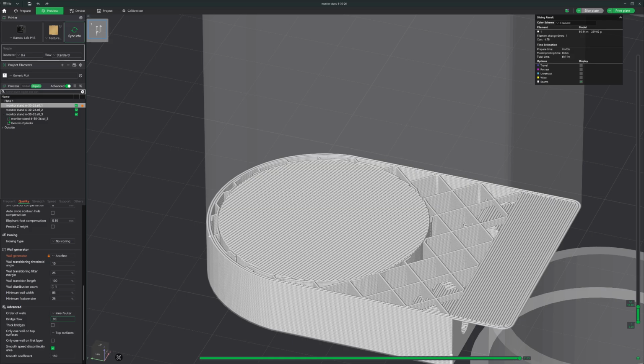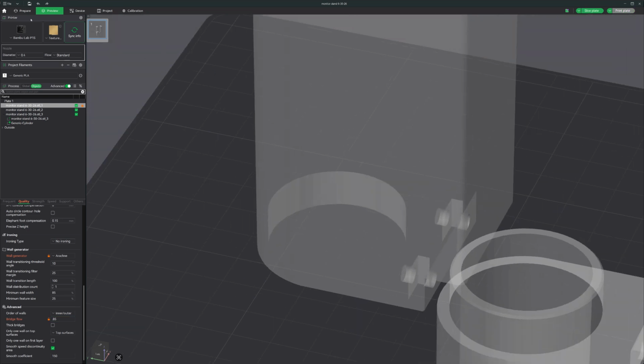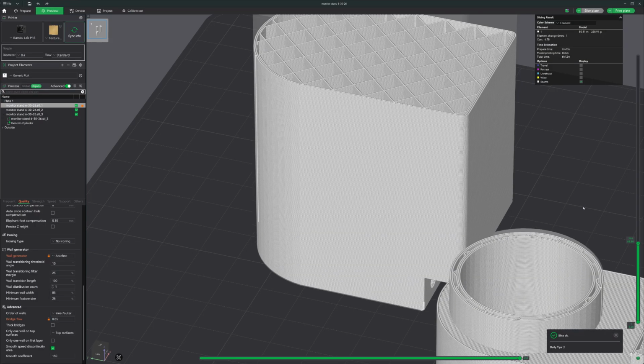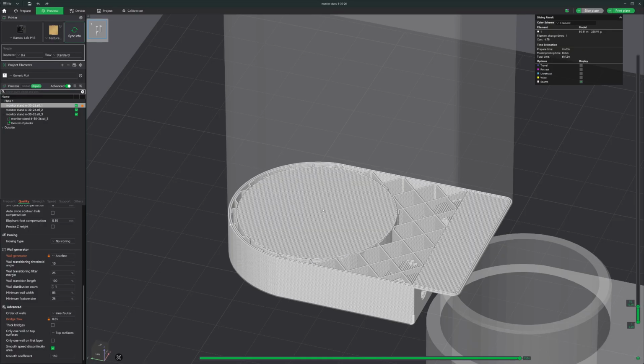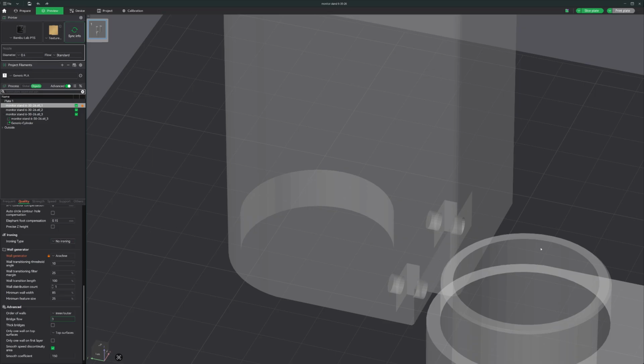If you ever are having trouble and you need to print a certain section of a print so you're not wasting all the material, you can come over here and set pauses. Let's say I just wanted to print this one section of this part for this bridging right here, for me to dial in. Set it at that layer height, and I come over here and do an add pause. So whenever I run the G-code and it gets to this point and it's done, it'll stop. And I can evaluate it, and then I can stop the machine altogether if I want to, change some other settings, and re-upload a file again. But for right now, we'll go ahead and get rid of that. And we'll actually go ahead and get rid of this bridging because we are going to use supports for this.